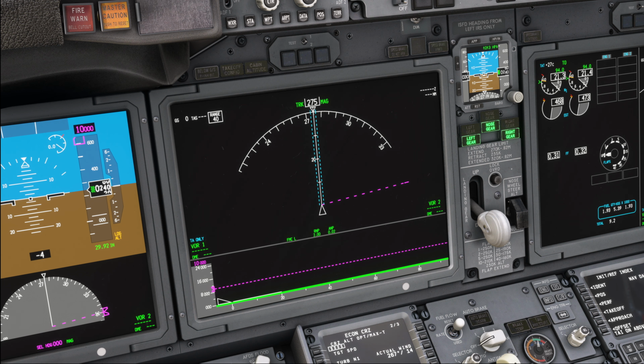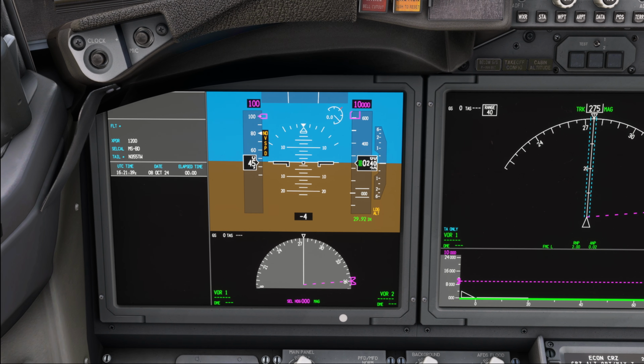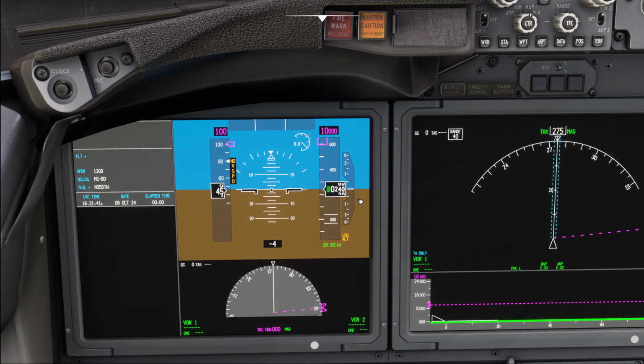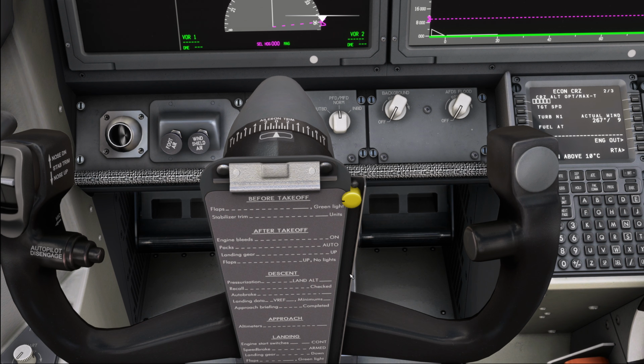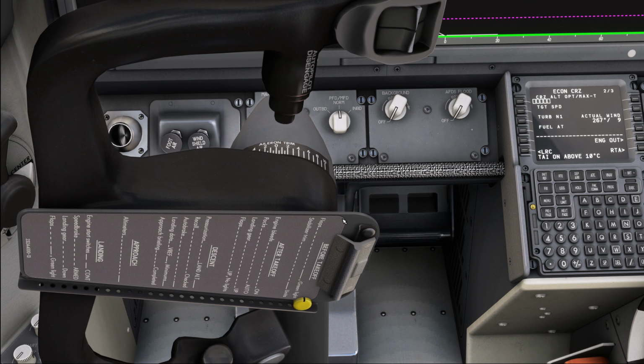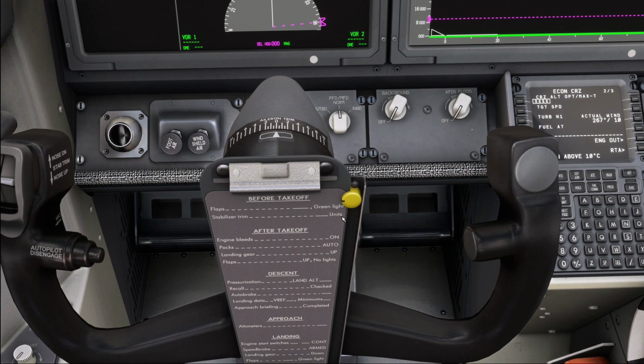What is new as well is an autopilot roll saturation alert that we can find on the primary flight display. Now, if the autopilot reaches the limits of what it can do, you might get an alert that is called out orally, "roll authority." And this indicates that the autopilot is reaching 100% of the authority that it has. So it has turned the control column all the way to the side like this, and it is not able to hold the airplane in its position.